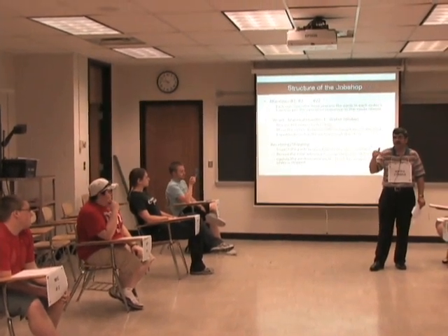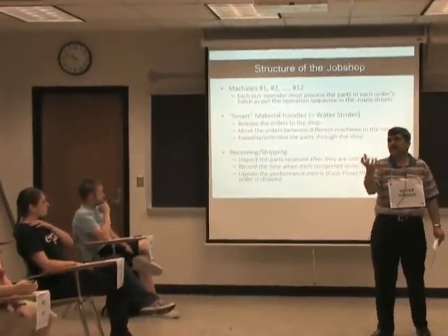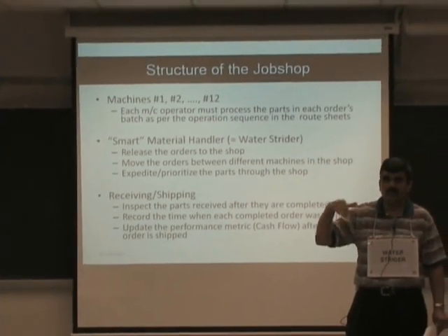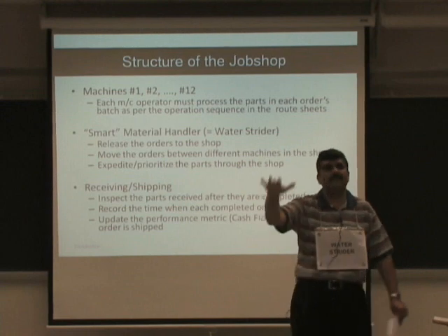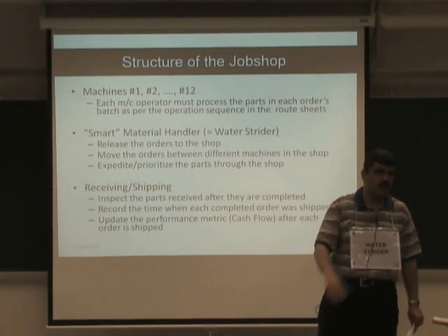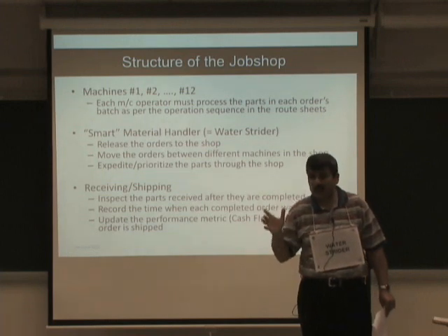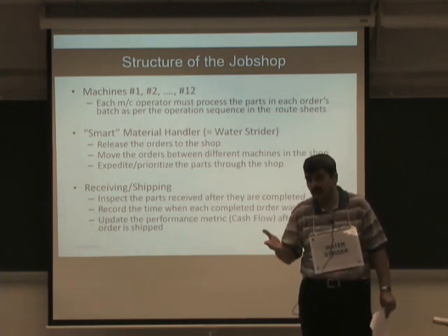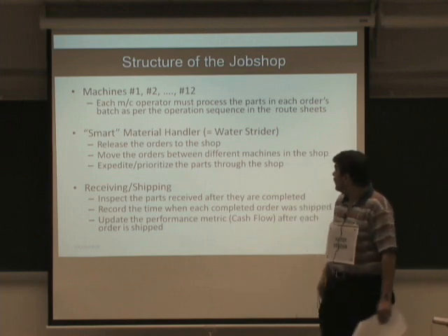So to that extent, just be diligent, that you cannot be a grinding machine and get a rough forging. You blast your machine apart. Grinding machines require you to first remove most of the metal off the raw stock, and then you kind of finish off the part. Okay, so that we should know that all layouts are designed around sensible choice of process flows. Most choices aren't sensible, unfortunately, and that's why what you have are badly designed workflows in most layouts.